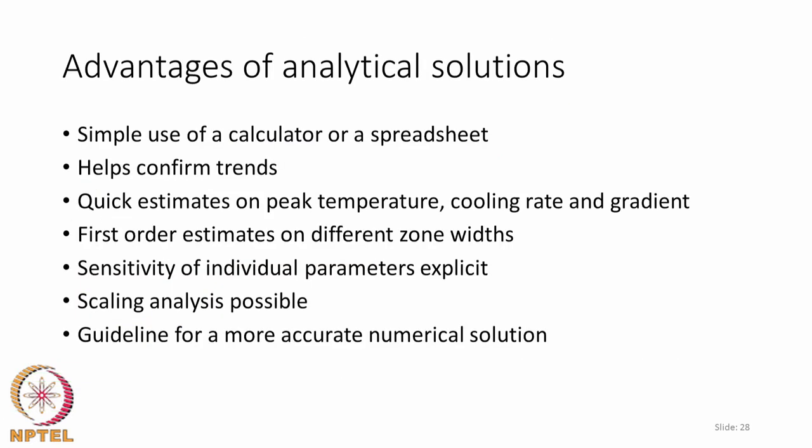Having now seen a number of analytical solutions that are available, we can appreciate the advantages of these solutions. The first advantage is that you can use a calculator or a spreadsheet like an Excel sheet or OpenOffice Calc to estimate the temperature profile. This means that without going to programming or numerical simulation, you can estimate the temperature profiles or the distances between two temperature contours, or, for example, find out the depth and width of the pool, etc.